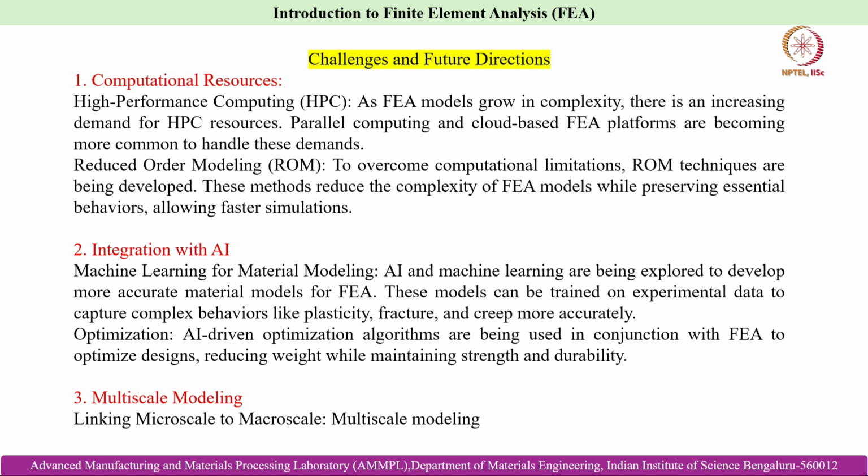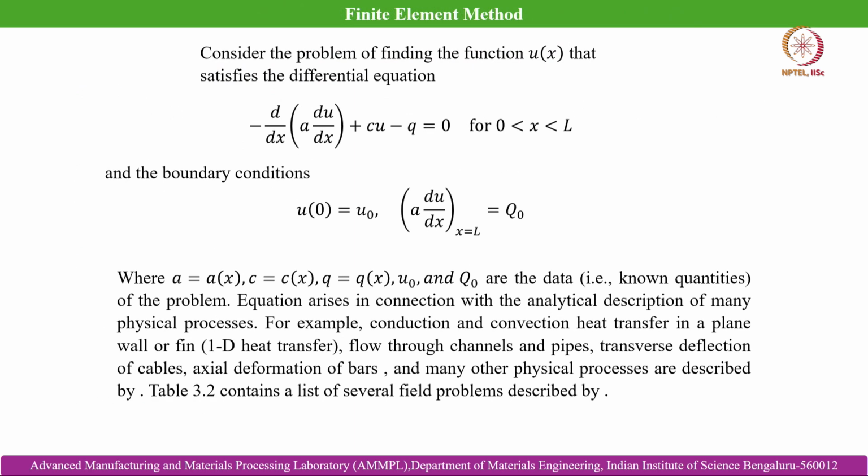microstructural information like primary and secondary dendrite arm size, and also how the different phases are distributed, what is the volume fraction of individual phases, what will be the morphology of the individual microstructural phases. So, if we can club both macroscopic and micro and even mesoscopic information at one place, then we call it a truly multi-scale model. So, that is the need ahead. And then, if we now start with the finite element.